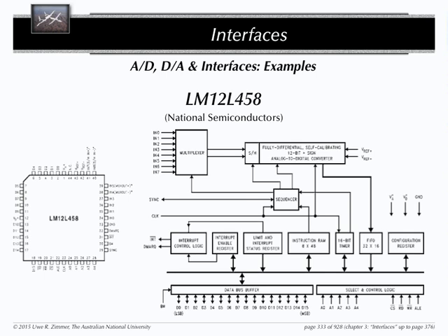What's A0 used for? It's in the data sheet so far. Yes, this is because what I have been showing you here is the 16-bit version interface of this whole thing. You can also run this thing in 8-bit mode, and in 8-bit mode, A0 is being used. In 16-bit mode, you always write in 16-bit, so A0 is ignored. So far, so cool? Makes sense?